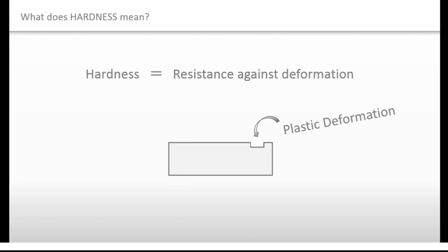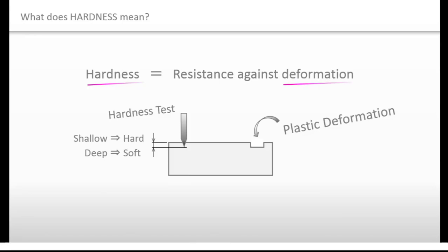The idea of this definition will enable you to understand some studies in material field more easily. Actually, in hardness test, you use a hard needle and press the material with standard force. The material is going to deform, and you measure the depth of the deformation to evaluate the hardness. That's why, if you'd like to know the exact meaning of hardness, you need to understand what plastic deformation is.